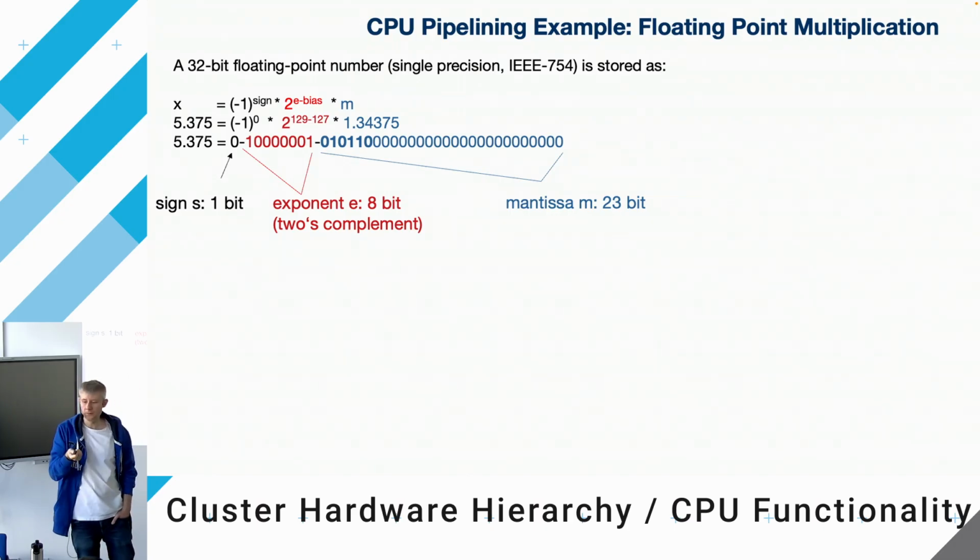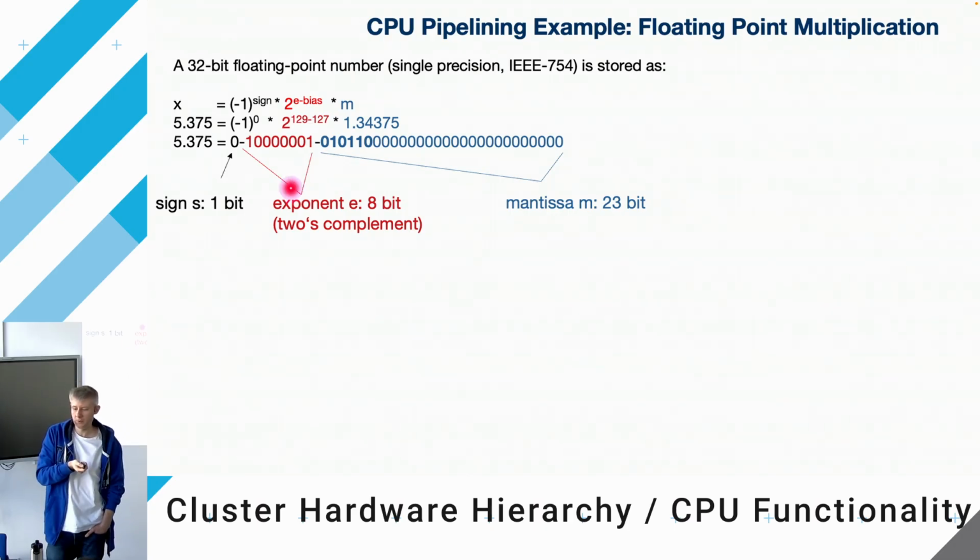They have a structure here. We have a sign bit, we have exponent bits here, and we have the mantissa here. So they have a format and the specification, the IEEE 754 specification, that is implemented in the hardware.